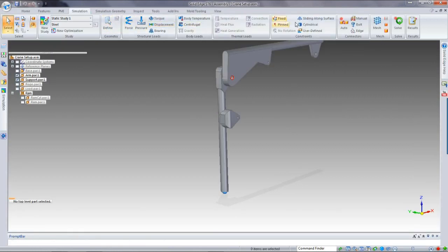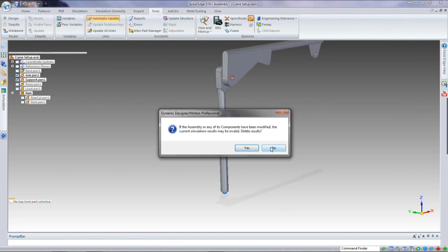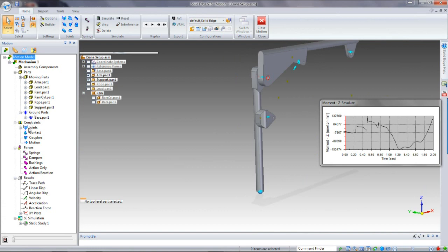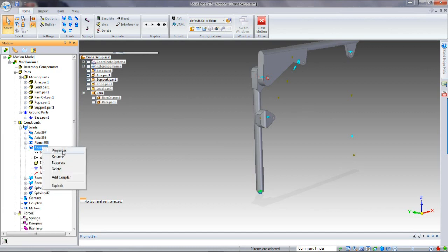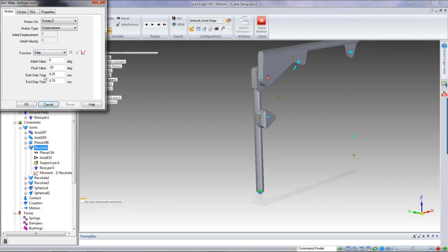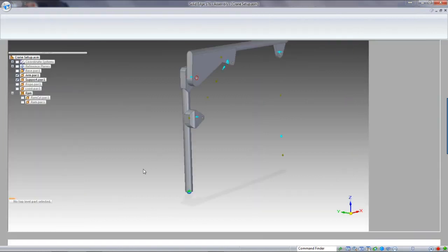While it's perfectly okay for the static load case, we need to put some limitations on the dynamic use of this crane. For example, we might want to put some limitations on the rotational speed of this. So if we want to do a check, then we can come back, edit the revolute joint, and change the duration, hence changing the speed, and we can then iterate that analysis to give us exactly the results you're looking for.